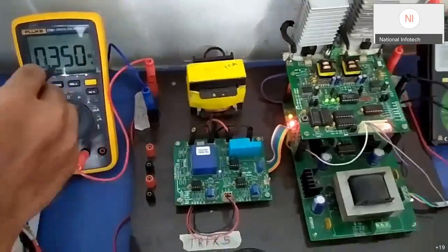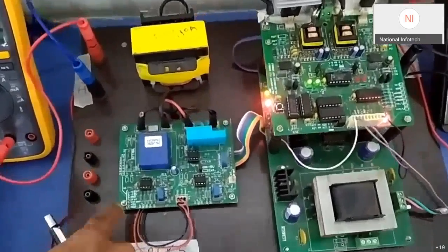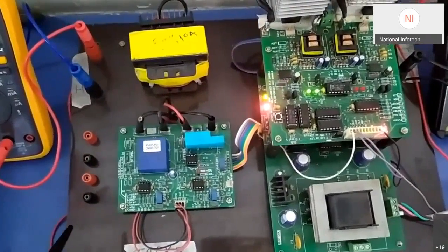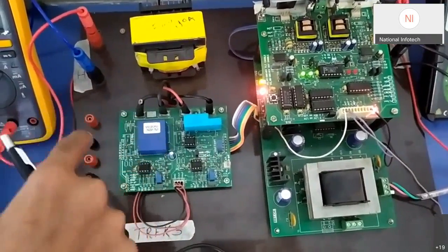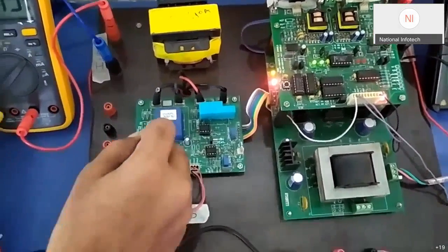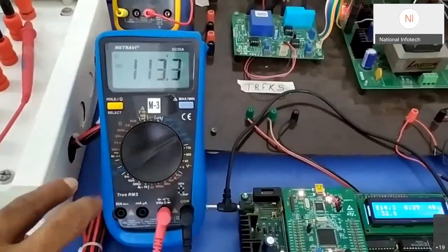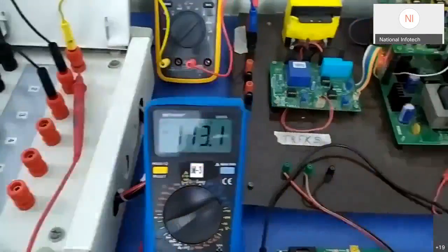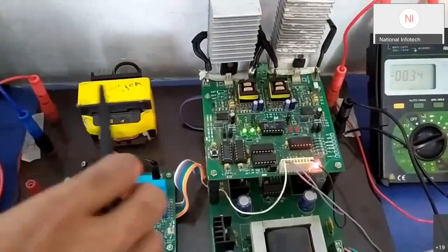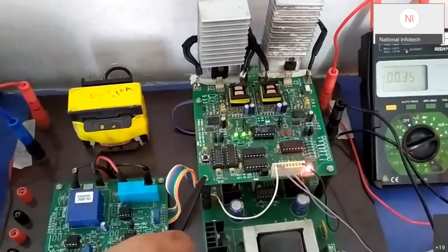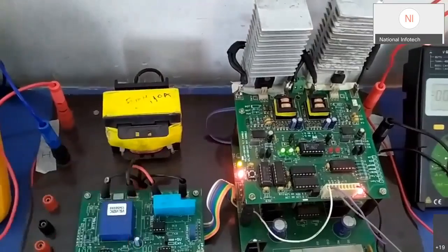So this is our input current, and this is our V3 sensor card, as we have in the DC sensor calibration, and it is connected in series for the current and in parallel for the voltage. The same voltage which we are sensing here is connected through the multimeter. Moving on to the boost converter, you can see this is the input inductor, and then this is our driver card for driving the switches. This inductor is of 5 millihenry and 10 ampere rating.